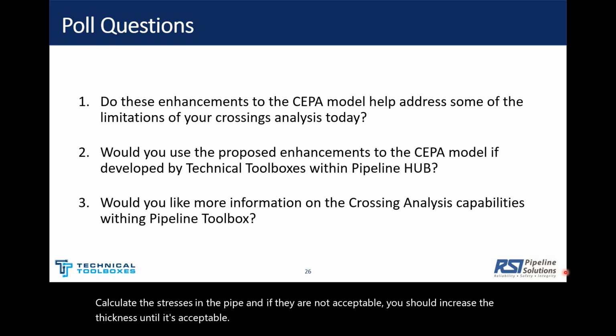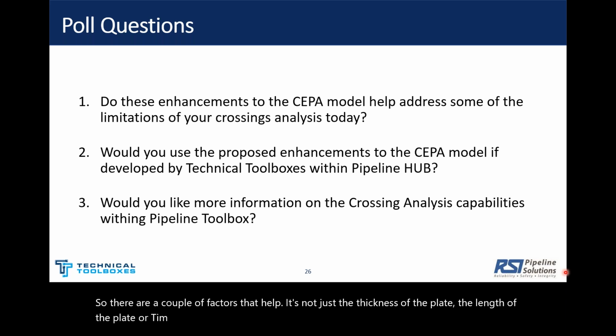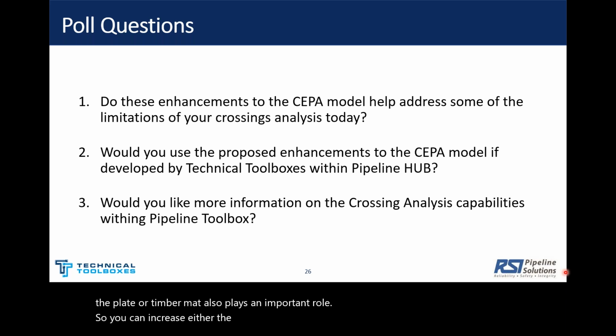So there are a couple of factors that help. It's not just the thickness of the plate. The length of the plate or timber mat also plays an important role. So you can increase either the length or the thickness until you get desirable results.